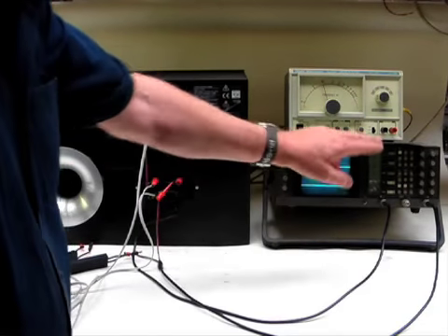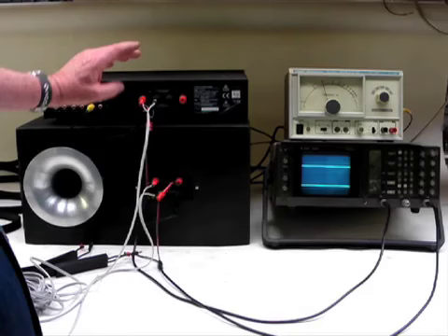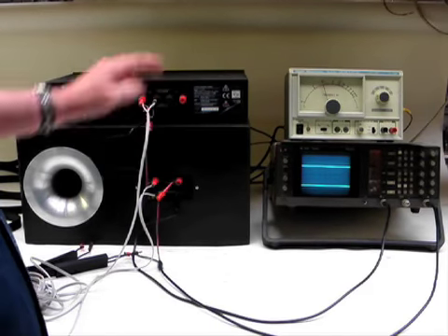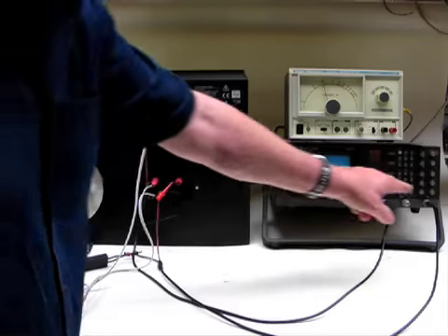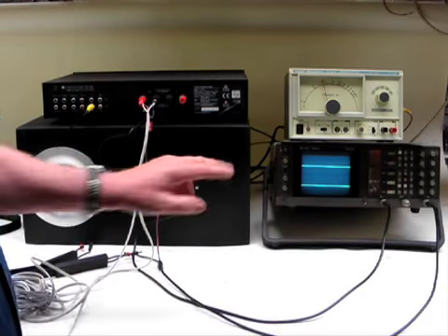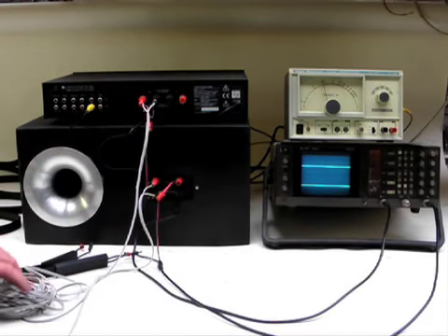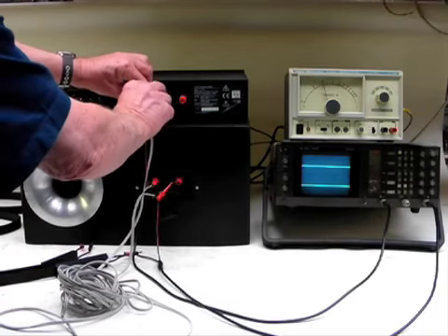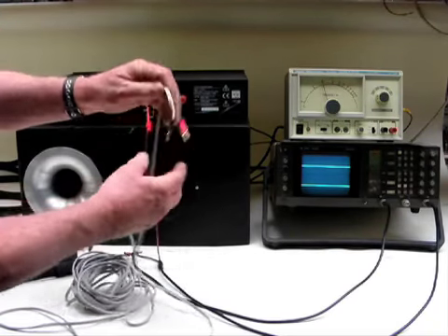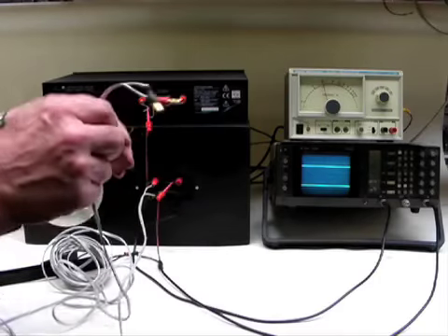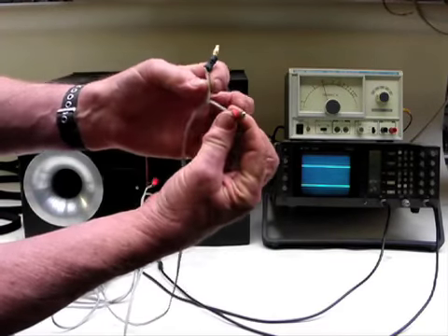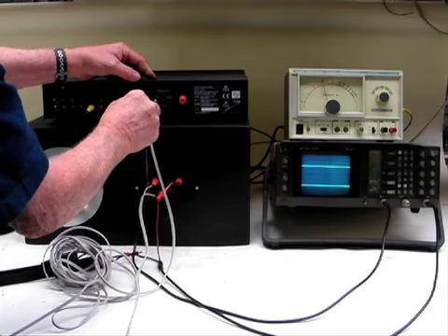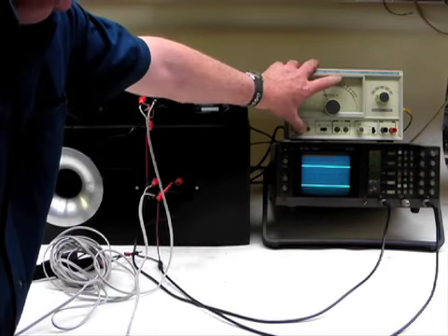Then we have a regular 2-beam oscilloscope connected. One beam, the top beam, is connected to the output of the amplifier, and the bottom beam is connected to the speaker. So we're looking at each end of the speaker cable. Now in this instance we're using a regular piece of figure-of-8 cable, which you can see here. It's just a very basic cable which we're connecting from here to here, and then we're going to turn on the audio oscillator here,